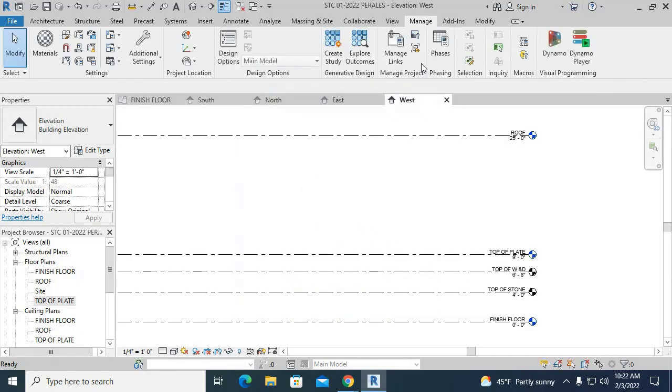Now, the last thing I'm going to show you today is that I want to update the precision of my dimensions so that when I dimension, it's something realistic. Okay. By default, it's set to dimension up to 1/32, which is crazy. If anybody's worked out in industry and looked at a tape measure, first of all, the tape measure doesn't go to 1/32. It's 1/16, just like your scale ruler in basic CAD. You've got to learn how to read the scale, or in blueprint reading, right? That's when we show the scale. Same thing here, the tape measure 1/16.